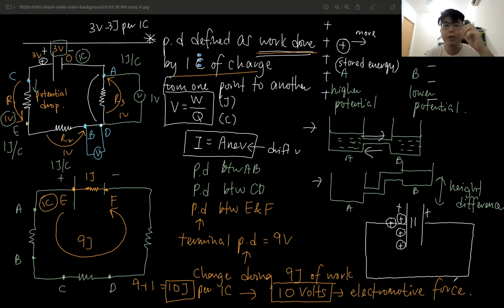How do you get the EMF? You have to do an experiment, get a bunch of values, and plot a graph. From the graph only, you calculate the EMF, which is the real power supply of the battery. As long as you are measuring, you always get the PD because there is internal resistance.